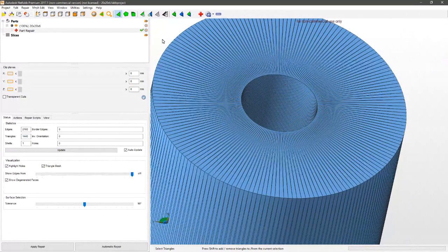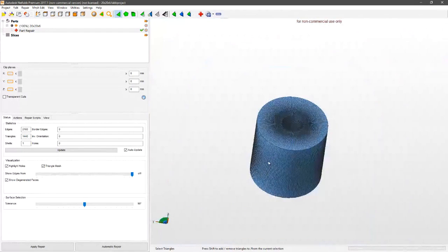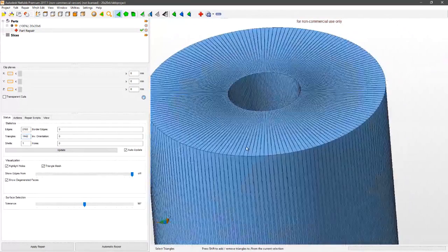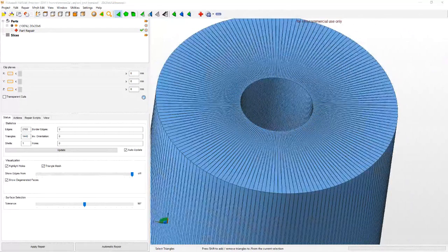So what you can do to avoid that is, first of all, if you're using CAD, just set the export options to less triangles, because this is a super small print, and it's 1,440 triangles, which is quite a lot. You'll be surprised by how many triangles certain models use up. Set the export resolution lower, or you can actually do that in Blender.